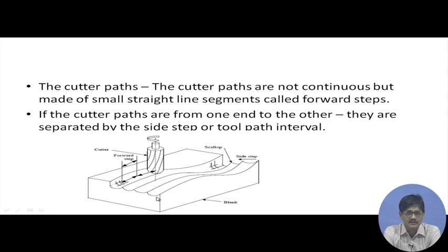The designer definitely must not have had these small scallops or upraised portions all along the surface. Yes, this was definitely not part of the design surface, but still you cannot avoid it, because the cutter while moving through will definitely produce these grooves.